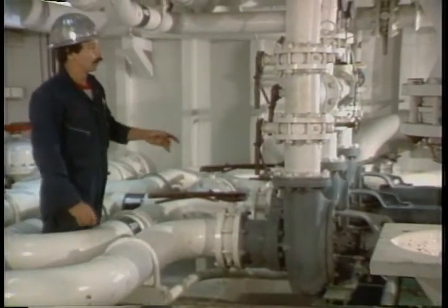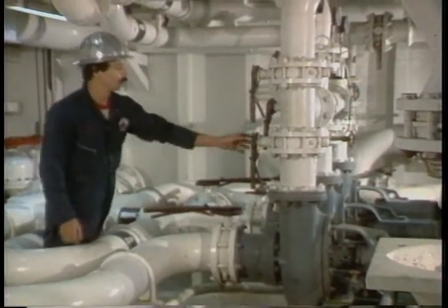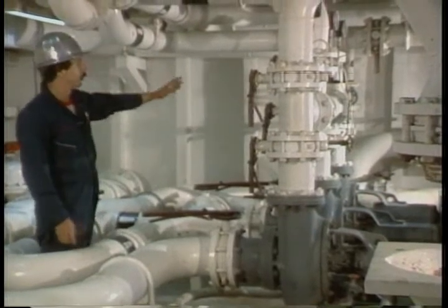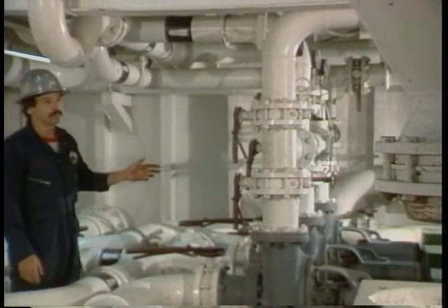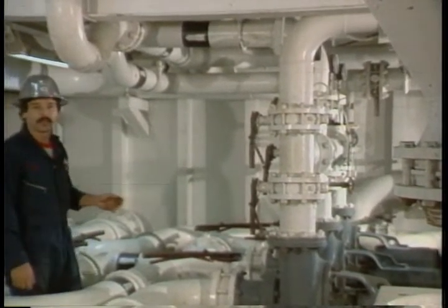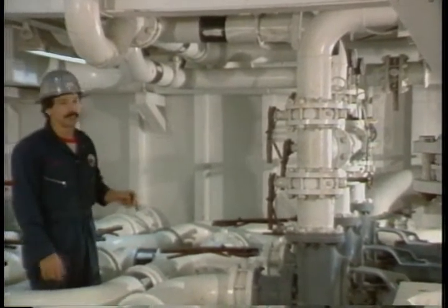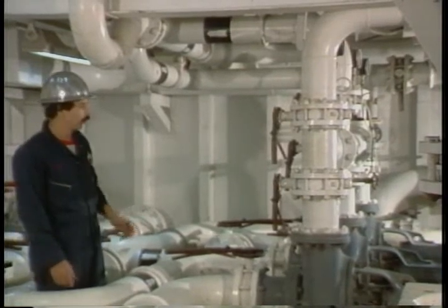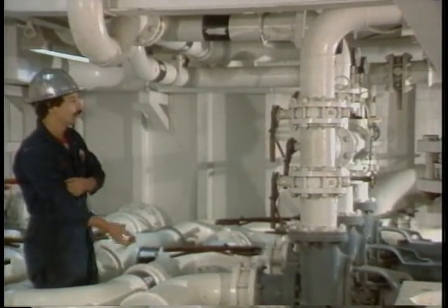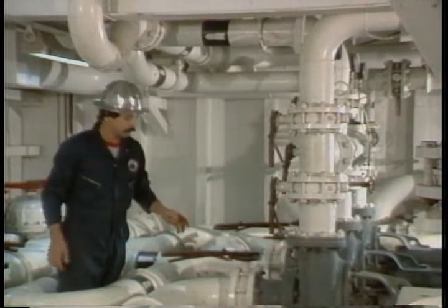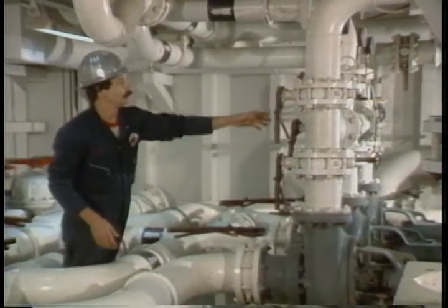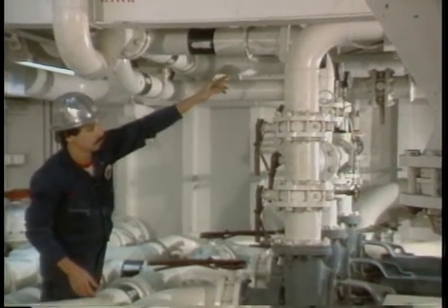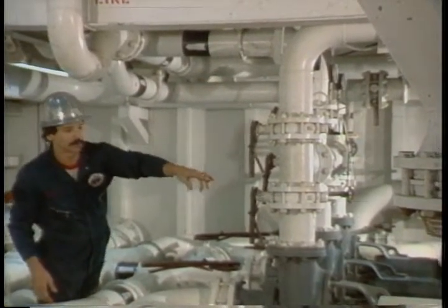When I turn the pump on, it'll then be discharging through my discharge manifold, which is this entire system here. This system enables you to transfer mud with any pump that you have to any pit, to various spots on the rig. The way I've got it lined up is after it's being drawn through the centrifugal, it'll be discharged through this line here, which is the line to my hopper system.